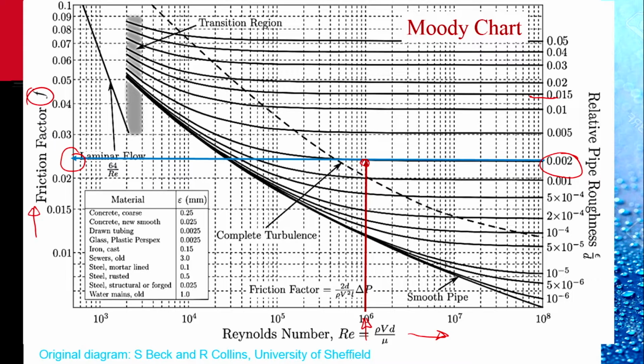So using the physical fact that the pressure drop should be proportional to the length of the pipe, we have been able to reduce the number of parameters on the right of the equation, that is the number of independent parameter groups, from 3 to 2.